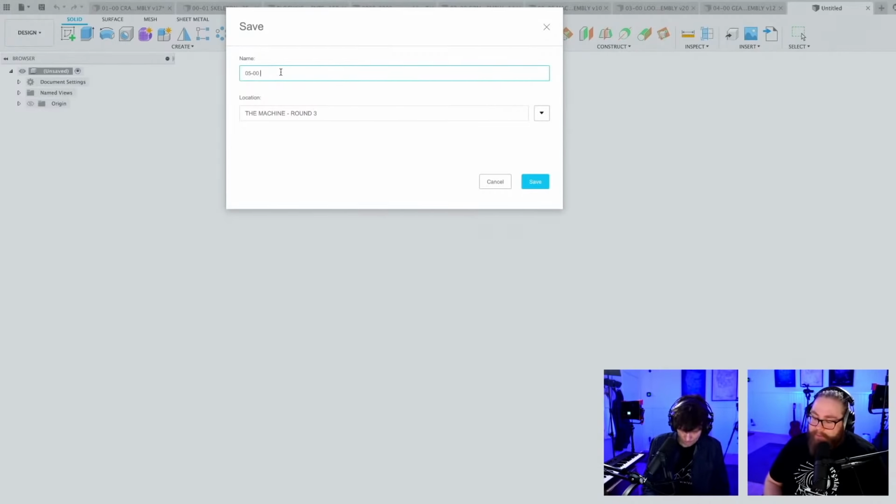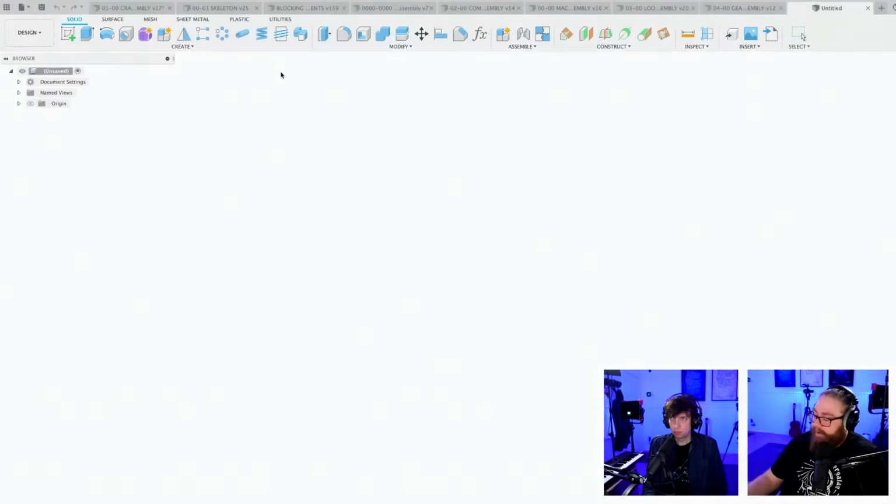A lot of people are saying it's great for noise with the belt, because gears make a lot of noise, if you want it to sound acoustically nice. And also Matt Schoen says that way you don't have to line everything up perfectly. So flat belts are very, very silent.